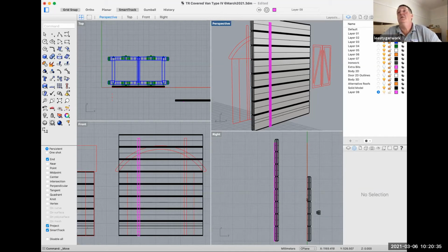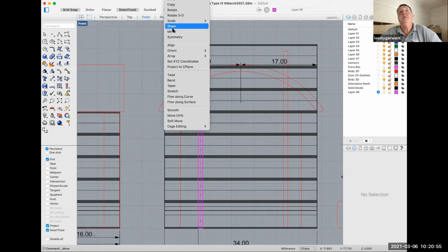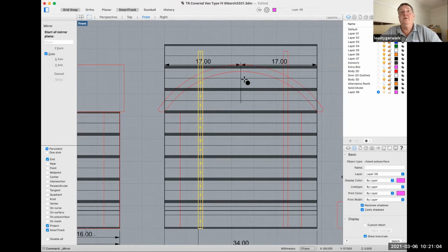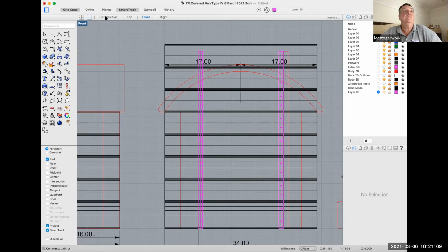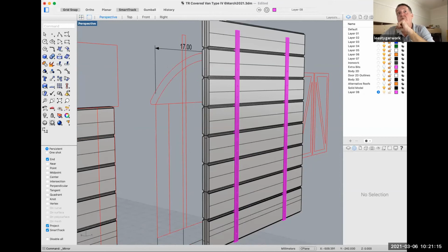Now, putting those rivets on was not a spectator sport. So very, very quickly, what we're going to do is create a new one. There's 2 dimensions here. And the reason I've just pulled those up on the default layer where all our dimensions are, is that this is the little guy we're looking for, which is a center line. All I'm going to do now is go up to transform again, where we just had move, and down a few more is a thing called mirror. I can choose our solid. I hit there. I pick 2 points up on our center line. And hey presto, we've now got 2 of the guys. Get rid of the dimensions because they're just irritating.